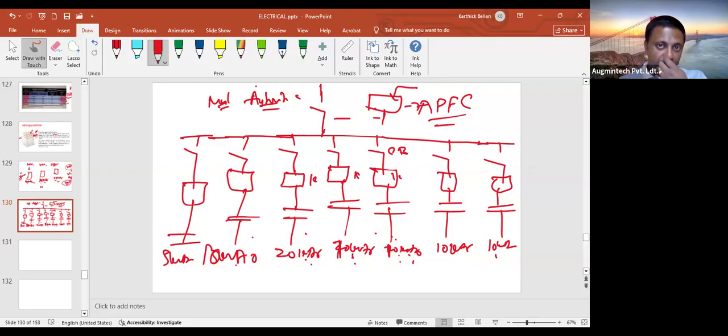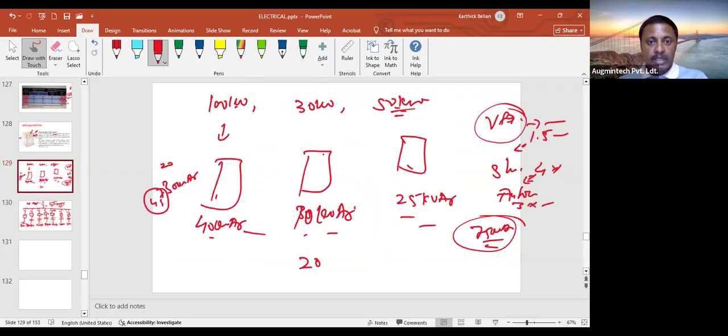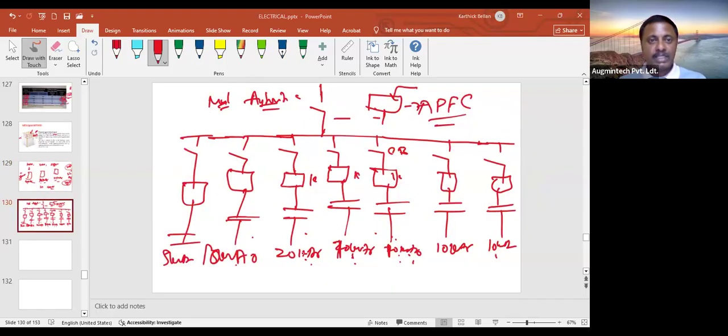That's the reason we have to split these capacitors rather than directly providing for each and every motor. Even if 40 kVAR capacitors are available, it is still a best practice to split them. If we split the capacitors and install them, as per the actual requirement, it's going to get adjusted. So this is how we have to design the capacitor panels.